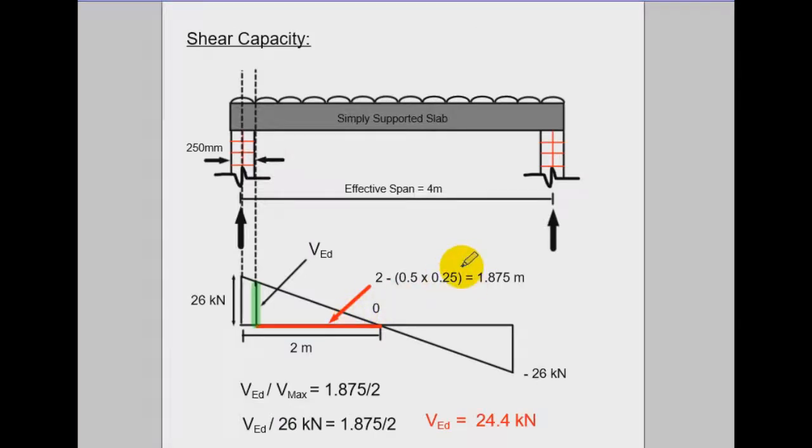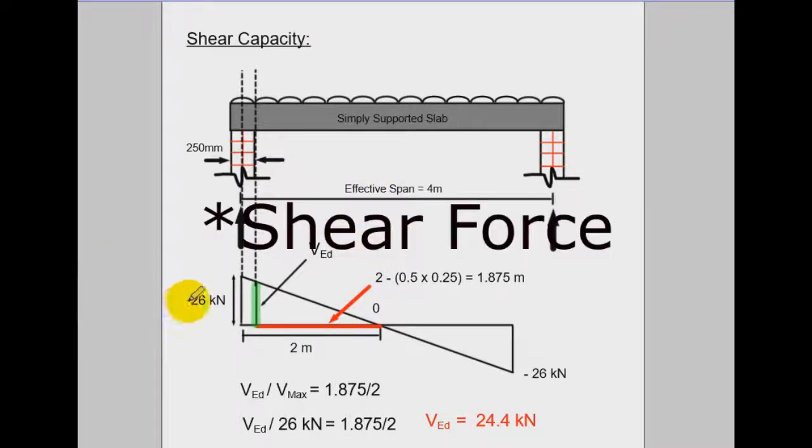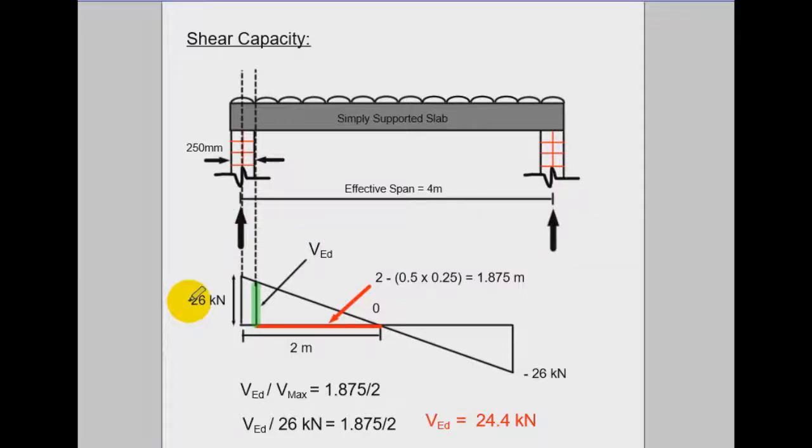Okay. All right, let's just check the shear capacity. Remember, when you are designing a slab, then the shear isn't really that big a deal. Usually the slab has enough capacity to resist any kind of shear stresses, without considering any kind of shear reinforcement. So we have the shear force, which we worked out very early, and it is just at the center of the support, but we don't need this shear force. The one we need is this one here at the face of the support.